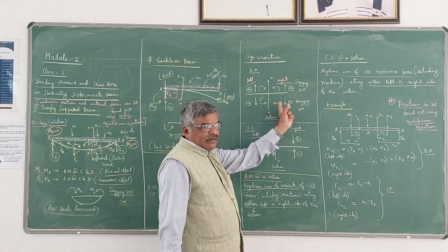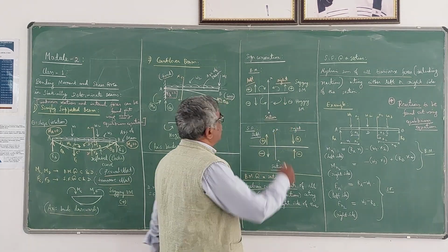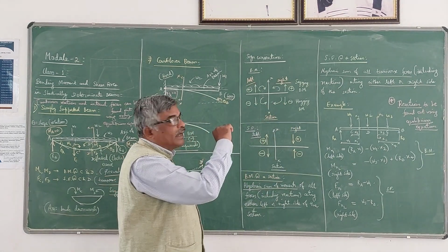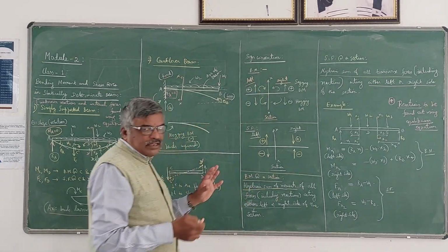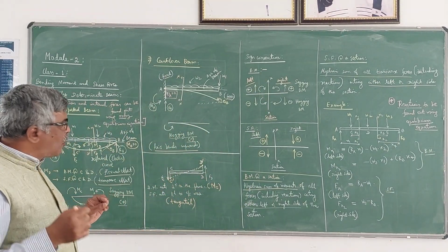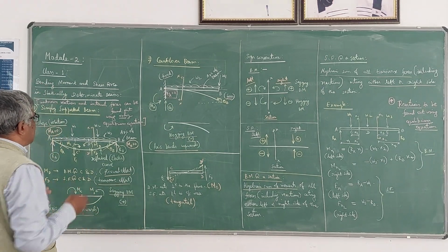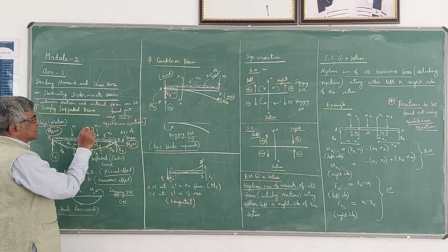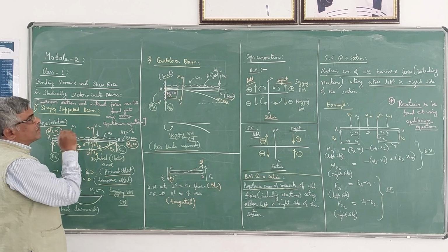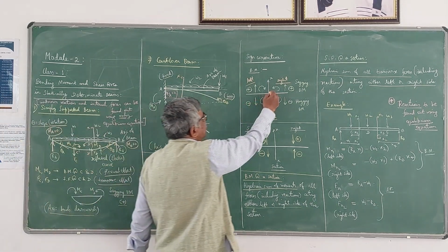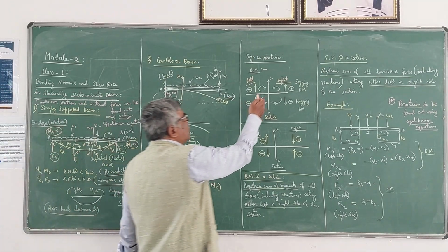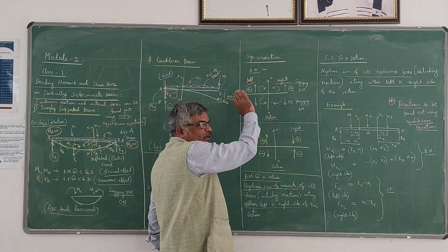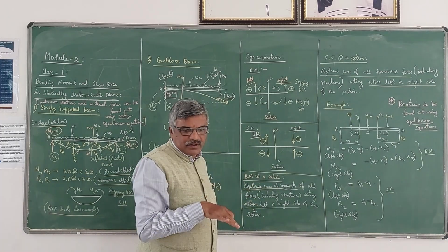Now we have to use sign convention. So in brief, for doing problems, we can take it like this. For bending moment, the sign convention is, so always bending moment is calculated at a particular point or a section. Now I have taken a section here. XX is the section here, section XX. So here, if you want to find the bending moment at the section XX for this beam, you can either take the left side of that section or the right side of that section.